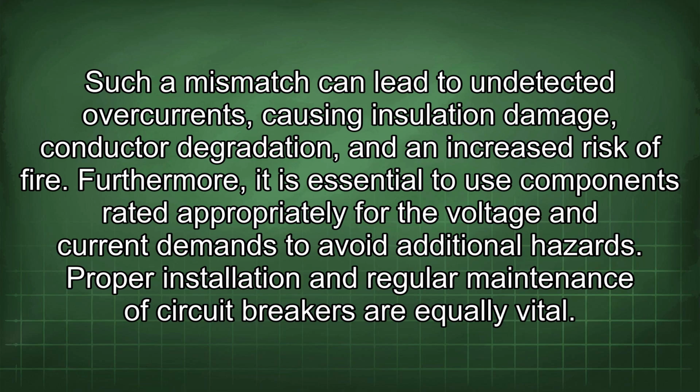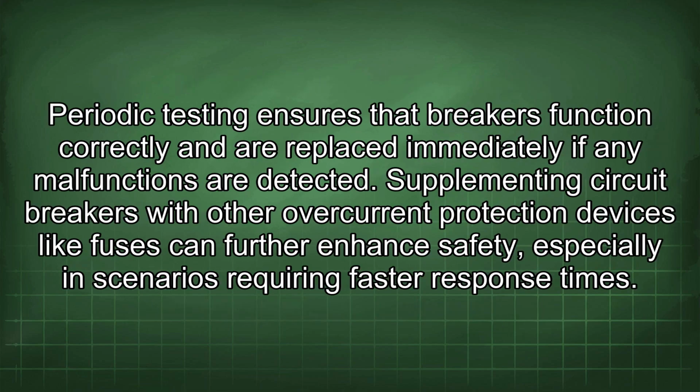Furthermore, it is essential to use components rated appropriately for the voltage and current demands to avoid additional hazards. Proper installation and regular maintenance of circuit breakers are equally vital. Periodic testing ensures that breakers function correctly and are replaced immediately if any malfunctions are detected.